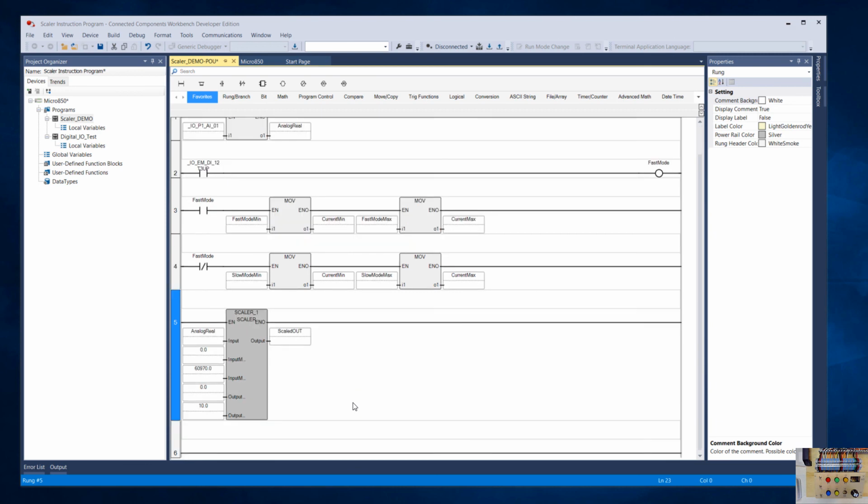But let's say I have a process that runs at 60 feet per second, and I want to use my potentiometer to adjust that down to maybe 55 or up to 65. So I could do that still using only positive numbers by setting my line speed to be at 55 feet per second and then adding up to 10.